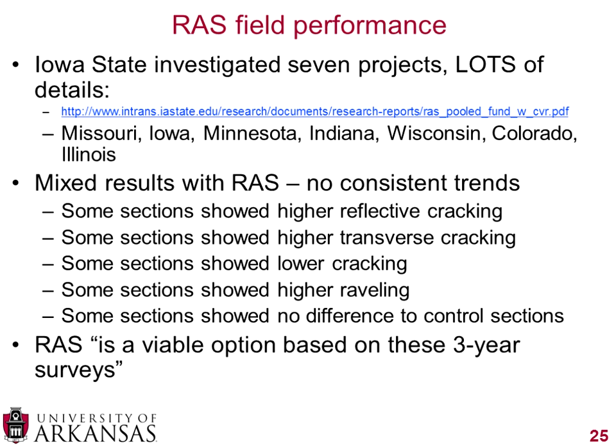So there's kind of a mixed bag there, and that can either indicate that RAS really doesn't have an effect, maybe something else is driving it, maybe there's another behavior of that material that overpowered the RAS, or it may mean that the addition of RAS, and I believe that none of these were more than 5 or 6% RAS by weight of entire mix, so maybe there wasn't a high enough level of RAS to actually influence the end product.